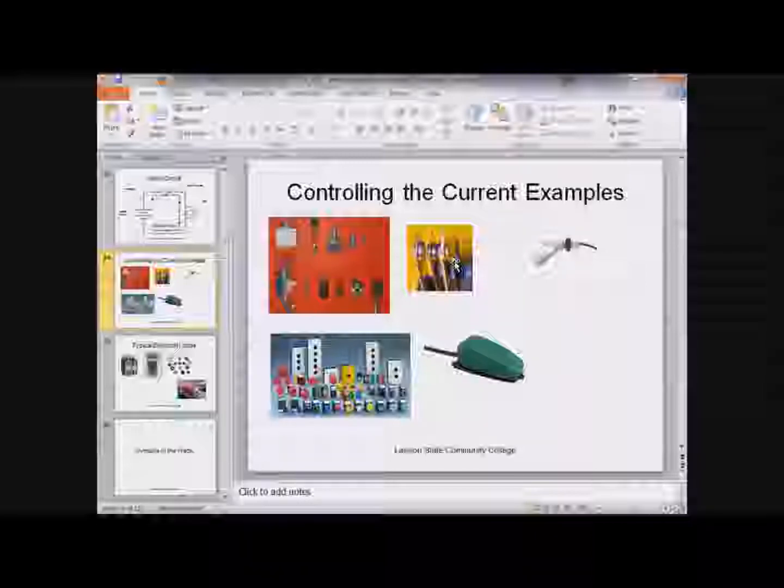And if I'm going to output an analog, if I want to control an analog device, like the speed of a motor, then we have digital to analog converters, where the computer or the PLC can actually develop a binary number, store it into that digital to analog converter, and it outputs an equivalent analog value to control the speed of the motors, control temperatures and stuff like that. The only sensor I have up here in this old picture is that little float sensor right there. And y'all know what float sensors do. If you've got a commode in your house, you've got a float sensor, probably.